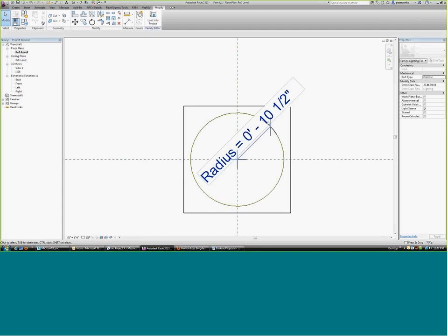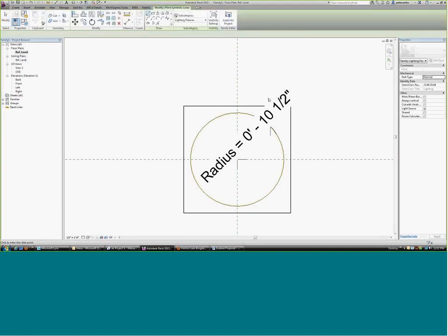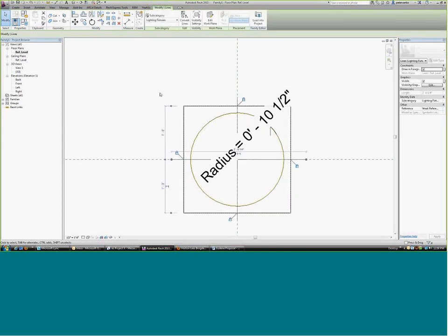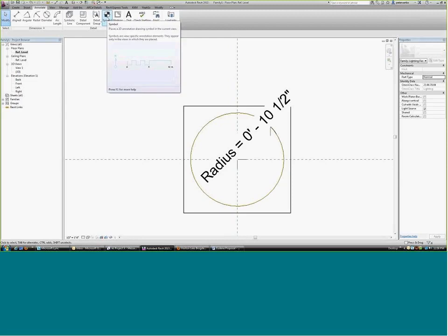It would only be giant because we were using a symbol, which is a very standard practice for the MEP suite, so that the symbol is always the same size on a printed sheet of paper, no matter what the scale.